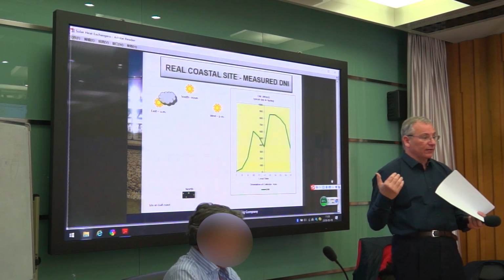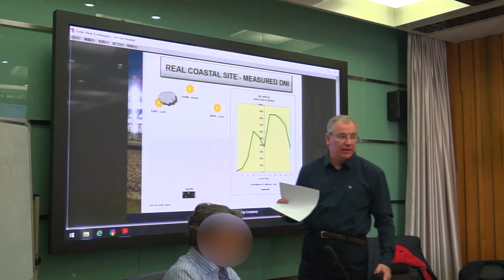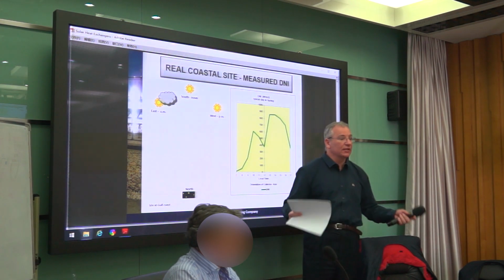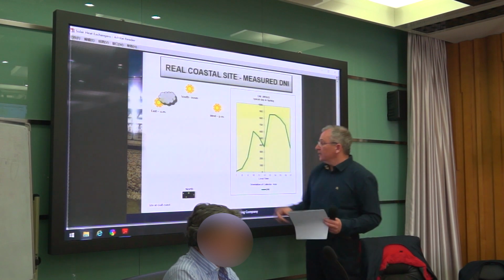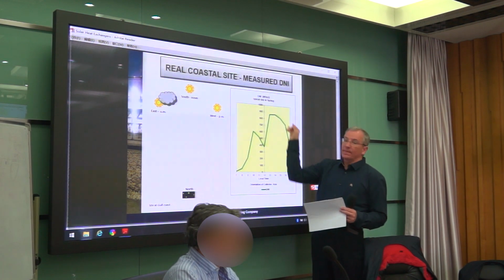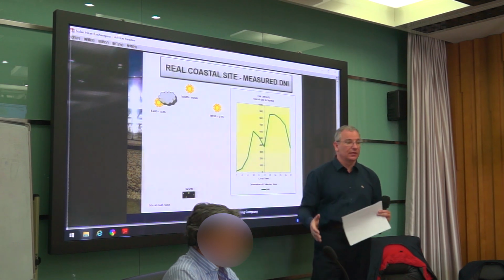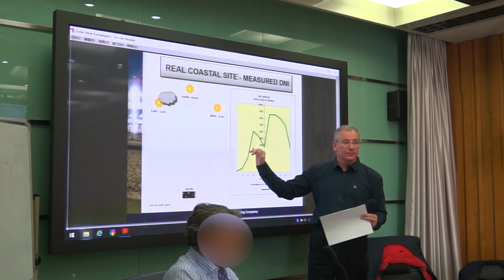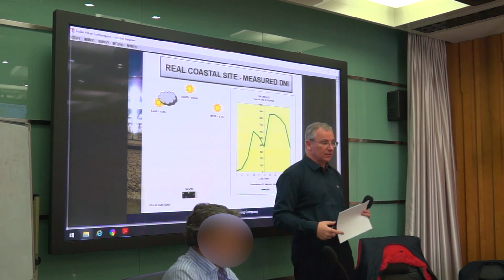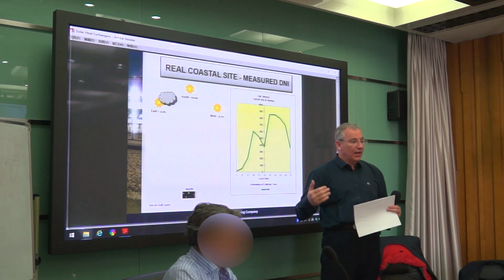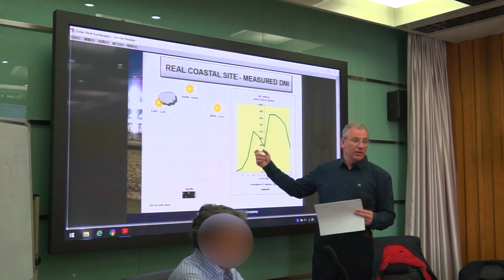That was the theory. Now we plotted for you these lines based on the DNI data or meteorological data for the real site, which is the coast side in the Gulf area, and you see you get some sun in the morning and in the afternoon. It is not absolutely theoretical that in the evening you don't have anything. You get some energy, but not so much. It is close to the sea, and therefore the effect of haziness in the morning is mirrored here.